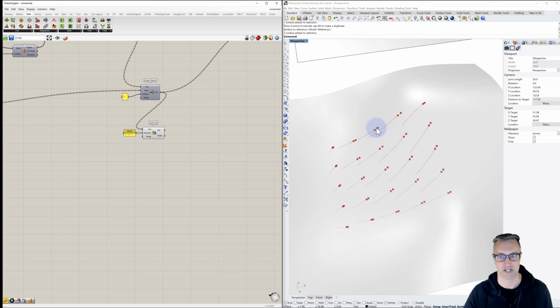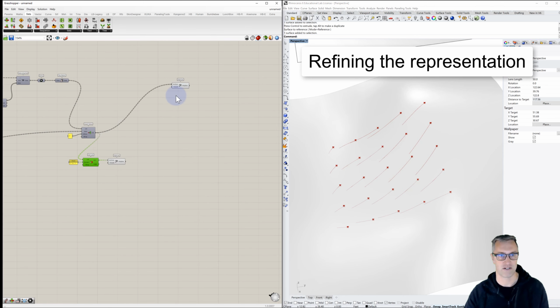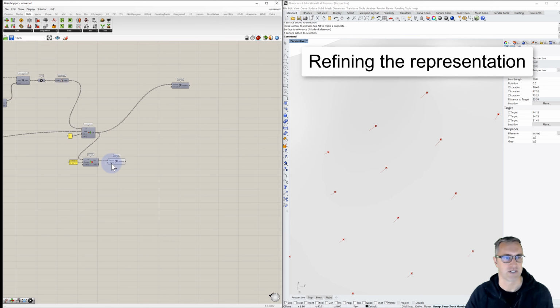And so now we can see we're getting 0 and 1. And what we can do with this is we can make a small polyline using those points. So we'll use the list, we'll plug that into here. We can hide these. We can toggle this. Well, actually we can hide our polylines for a second and just keep our short polylines. This is going to give us a vector, and we can use that vector to make a plane.